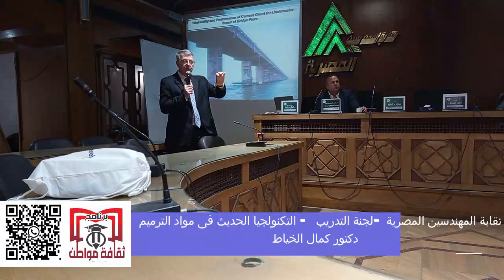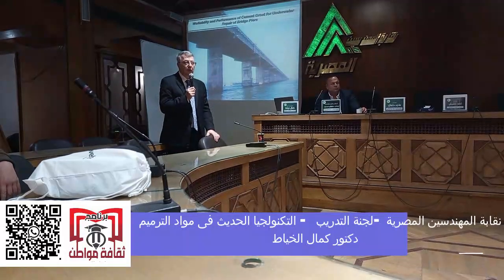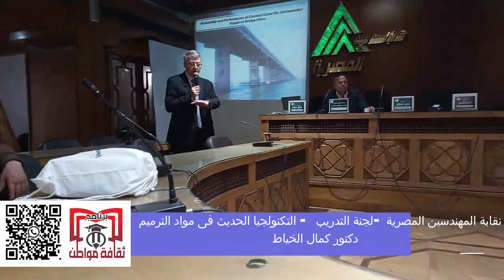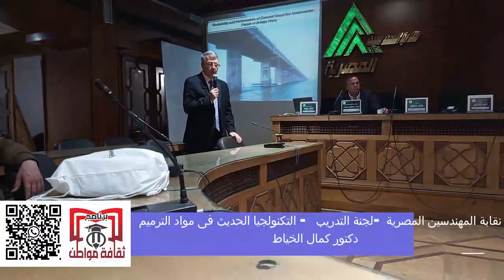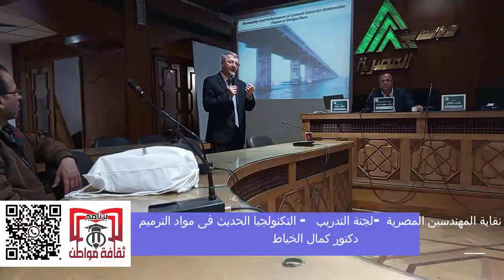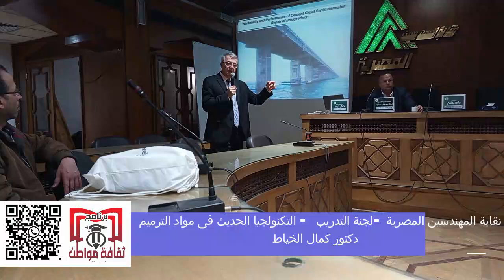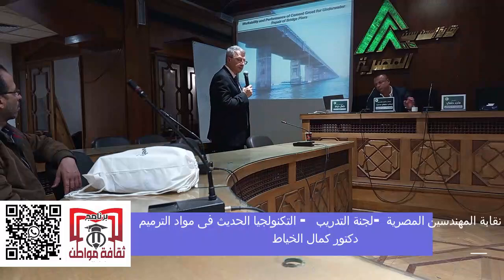So you design for the worst case. In this case, it's the St. Lawrence River. There's no salt. But the water line has some abrasion from waterborne debris, sand, and ice abrasion. But the cracks that you see there are mostly corrosion and alkali silica reactivity. I want to take you underwater next.